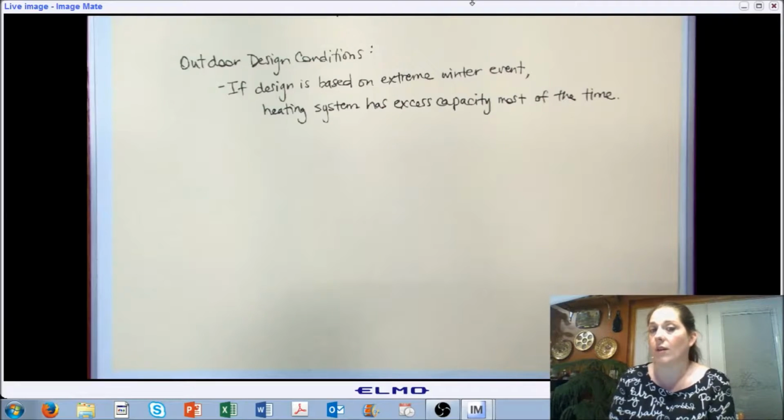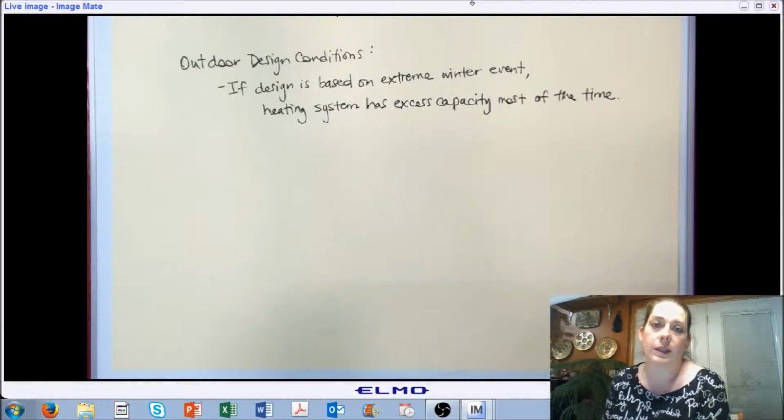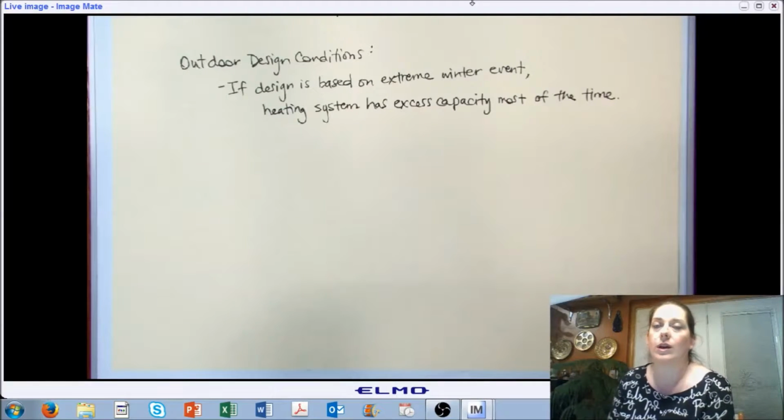It doesn't mean that all that time is consecutive. It's the accumulation of all the time throughout the year that you won't be able to maintain the set point condition. So depending on your scenario is how often, how much of that time you can tolerate. Typically in residential homes and things, we will tolerate the most amount of time outside of those conditions.